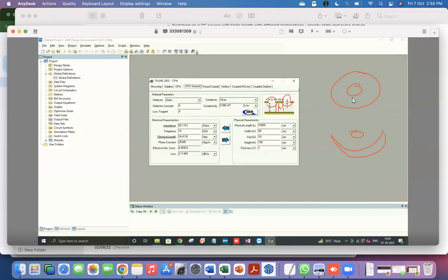So remember again, the thing I've been going on and on about, if I give a potential to a section of metal at one point, it doesn't mean that even if it's a perfect conductor at RF frequencies, the potential can't change along it, if your distances are comparable to the wavelength. So in order to keep the two ground planes on either side at the same potential, what one actually does, let me actually draw this here in a bigger size.